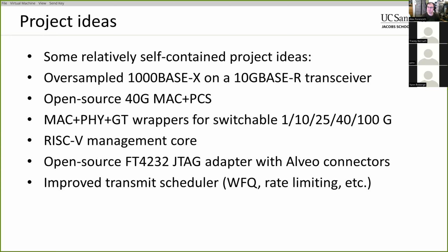If you wanted to use something like the Zynq ARM cores on Zynq devices, well, that might make it difficult to run PetaLinux on there, for one, if you want to use it for management. How do you reconcile that? And then second, you might need a bunch of Xilinx-specific libraries to configure everything properly. It would just add a lot of complexity to the build process, I think.